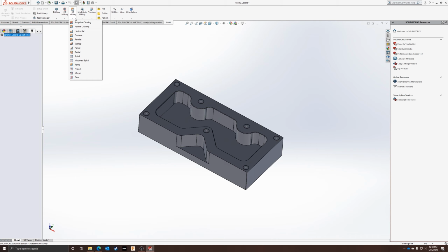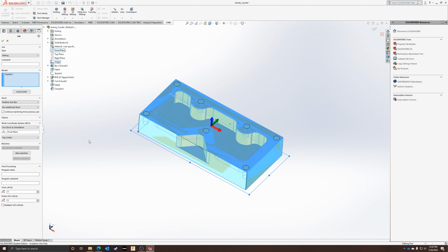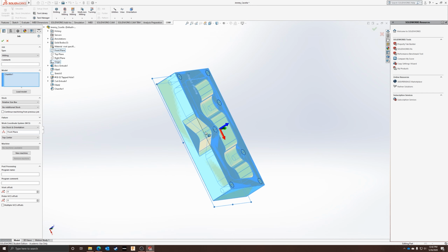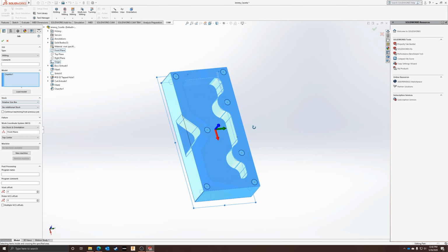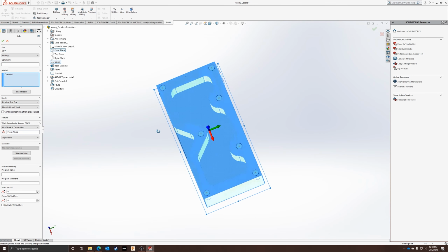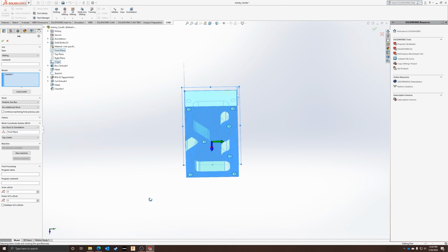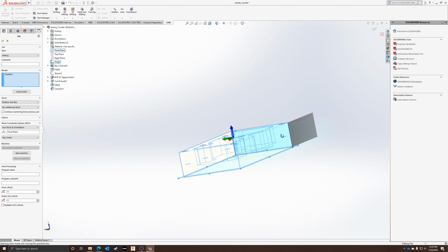These are all of the operations that are possible, but none of those can do anything unless they're placed inside of a job. And so the foundation of a job is it tells you what the material you're starting with is. It says your coordinate system, which, as we discussed in my presentation to you all before quarantine, was basically where the machine measures from. And this center is already set to the center top of the stock, right? And the stock is already set to a fixed sized box. It's just relatively slightly larger. A relative sized box. And that information is essential because it tells the machine what it needs to cut, so when to expect material and to start cutting. And it also tells the machine where to start from and where zero is.